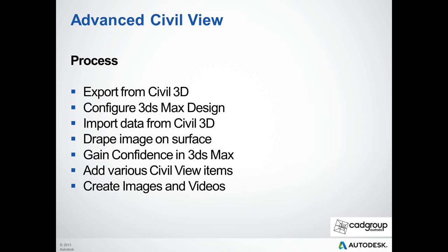I'm just going to take you over some of the steps where you can export from Civil 3D, configure some of the settings in Max Design, use some of the tools to actually drape images over topographical surfaces, show you some of the tools that will help you gain confidence in using the Civil 3D workflow in 3ds Max Design, and show you how you can create Civil View items like trees and cars, and then how to take it out and create images and videos.